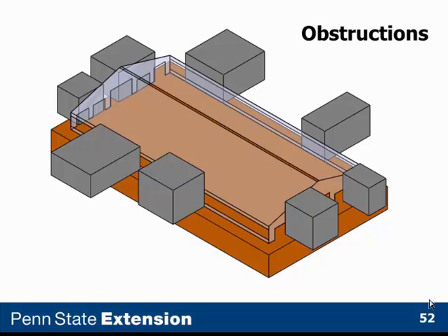These rectangular obstructions would represent, say, a milking parlor, or feed bins or silos, a bank of silos, or other attached buildings, or other obstructions to flow within, say, 10 or 15 feet of the building that would still substantially obstruct airflow to the barn above the manure pit.